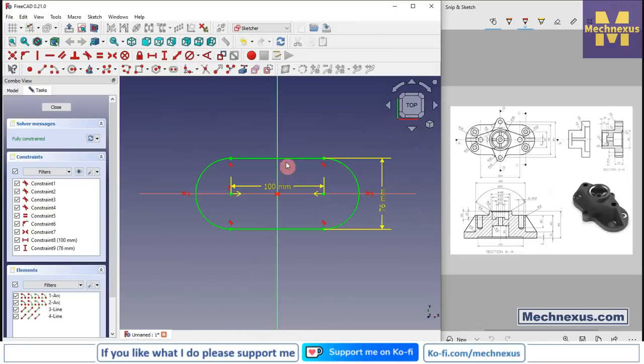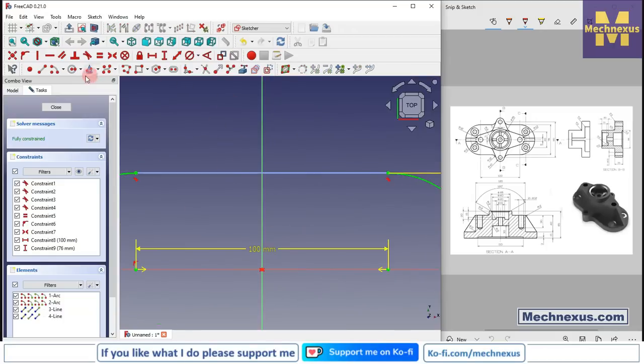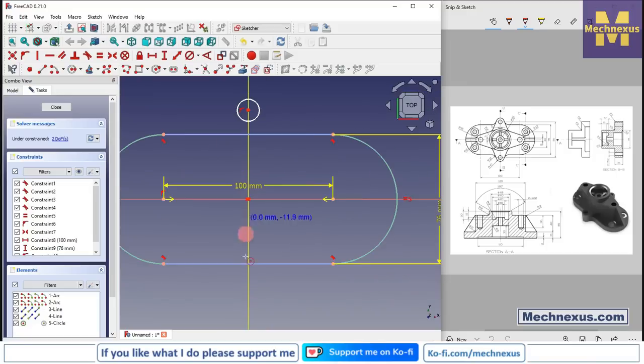and now we will select these two lines and make it a construction, and here we will draw the two circles, one at the top and other at the bottom, and we will make this center and this center symmetric.